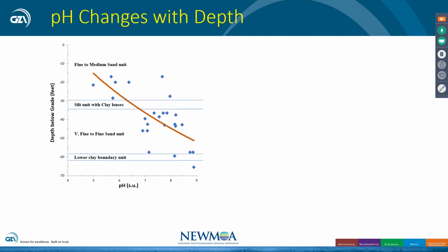So what actually happened here, we have to go back to our deposition. Remember I said that's very important. So how were these soils deposited? They went into the Lake Hitchcock. Lake Hitchcock's level rose and lowered. Those sediments went in. And what we actually had on this site that we were able to find is desiccated clays. So the contaminant actually migrated through the clays, and our assumption is that those clays actually stripped off a lot of hydrogen ions and created more of a basic condition.